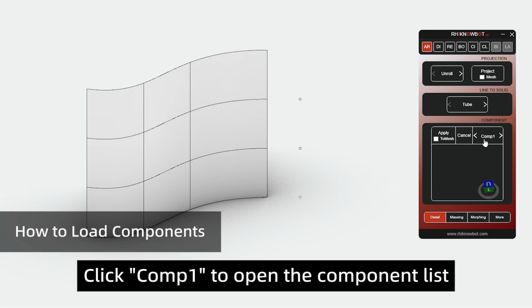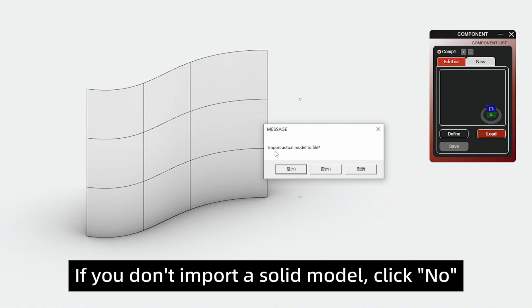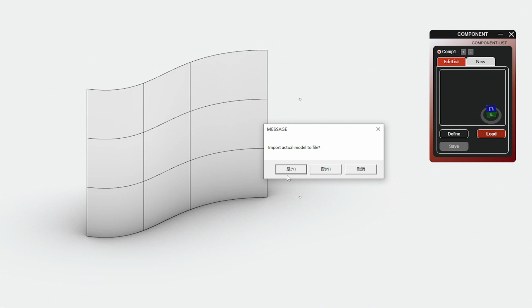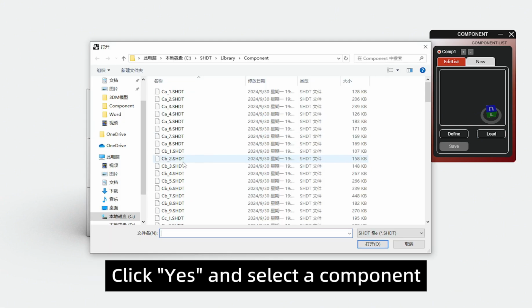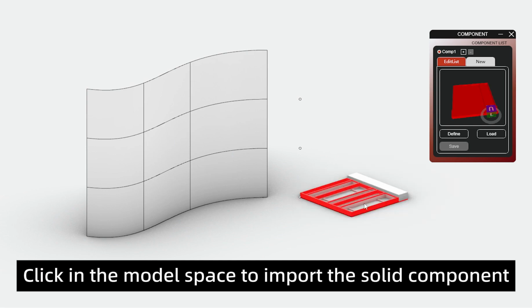Click Comp 1 to open the component list. Click Load to choose whether to import a solid model. If you don't import a solid model, click No. If you import a solid model, click Yes. Click Yes and select a component from the component library, then click in the model space to import the solid component.